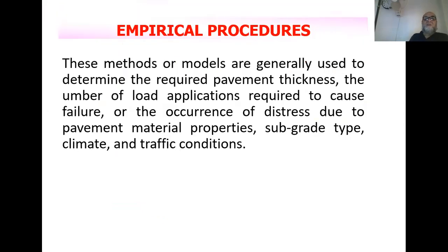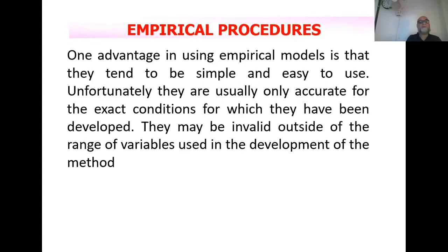Empirical methods are generally used to determine the required pavement thickness, the number of load applications required to cause failure, or the occurrence of distress, due to pavement material properties, subgrade type, climate, and traffic conditions. One advantage of empirical models is that they tend to be simple and easy to use. Unfortunately, they are usually only accurate for the exact condition for which they have been developed. They may be invalid outside the range of variables used in the development of the method.